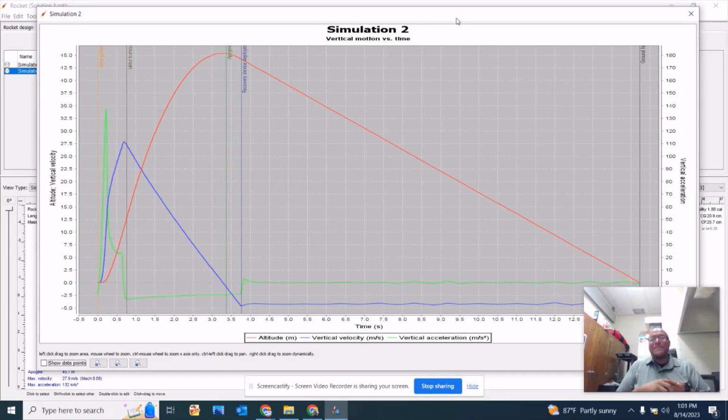We've had students who hit the 40 and 50 second time limit, and we've had some that got 4 or 5 seconds because of some rocket flaw or they didn't follow the instructions when we were creating them. All right. So, but again, let's get back to this apogee and recovery. Okay. So typically between a half second and a second, you want this recovery charge to blow out.